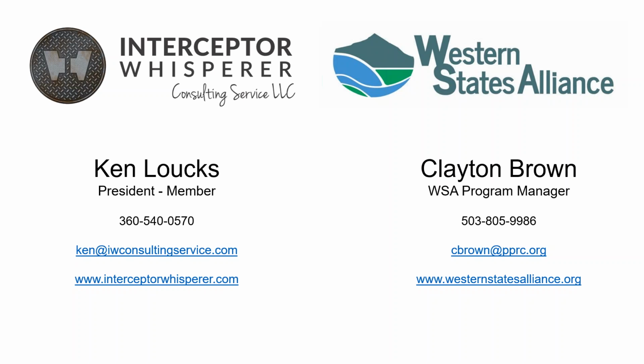A lot of the grease pumpers in the Portland metro area take their grease waste to either City of Gresham, which has a grease receiving facility at their wastewater plant, or Clean Water Services at the Durham facility in Tigard. There's also an anaerobic farm digester down in Tillamook County that is begging for grease because they put creamery waste and cow manure into their digester, and the grease helps that stuff break down and generate methane gas. So hopefully that helps answer that question.